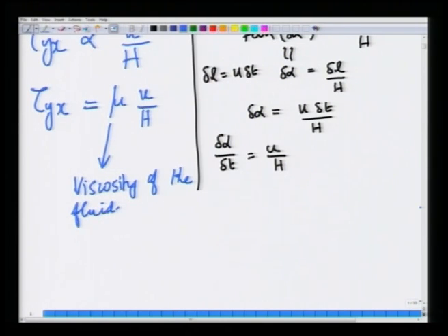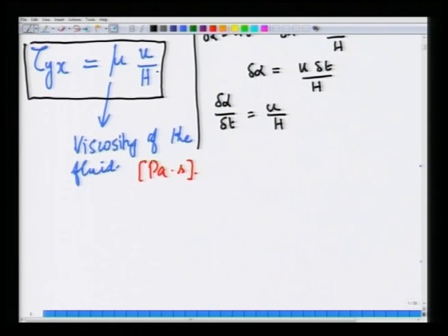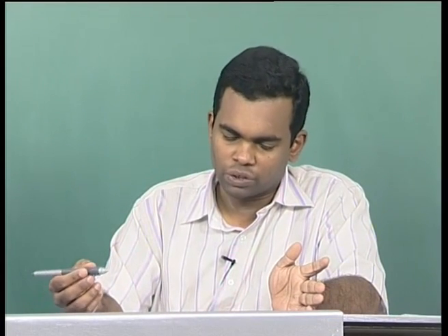We also gave you some examples of viscosity values. Viscosity of the fluid is measured in Pascal second in SI units. And we also gave you some examples of the values of viscosities of various commonly encountered fluids like air, water, oils and so on. Now, what is the use of this formula? Well, we will return to this formula in detail later when we do differential balances, but at the outset this is an introduction to how a viscous fluid behaves upon application of shear stress.